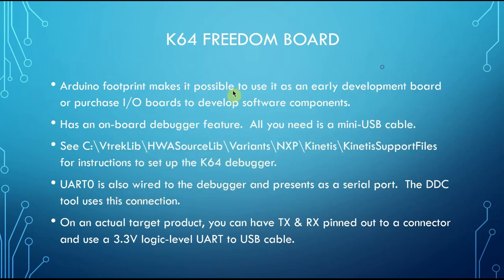There's also a UART port that's wired out to the debugger microcontroller, and it presents as a serial port on your PC, and the DDC tool uses this connection. But on an actual target, a product that you're developing, you can have TX and RX of any serial port brought out, pinned to a connector, and then purchase a 3.3 volt logic level UART to USB cable, and it'll give you the same capability.